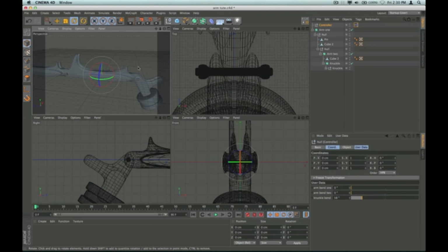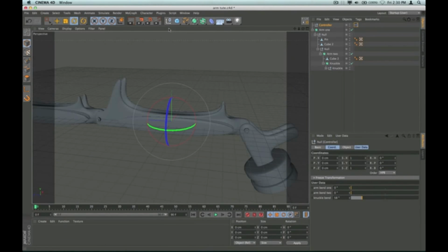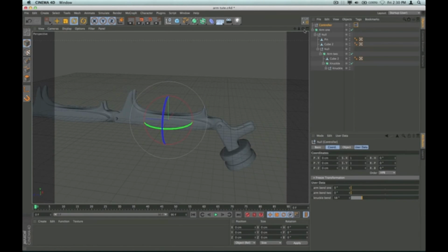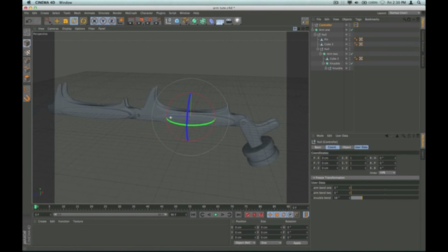I think we're going to call it quits for part 2. We did some modeling adjustments, some tweaking, and we modeled our knuckle. We moved some anchor points around so things would rotate from the right positions. We set up our parent-child relationships, and we rigged up the expresso.